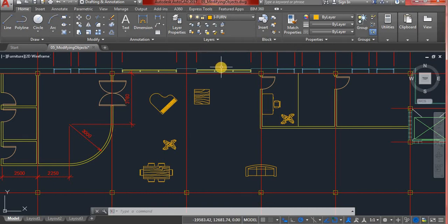One last type I would like to mention, just so you have a brief idea about it. We can type our selection. I don't have to click anything; I can type what I need to be selected. For example, I will pick the erase command. When it asks me to select objects, I'll type all. Be careful with that. It will select everything in that file that you're working with. It's just a test to see how things work. So when I type all, I'll press enter.